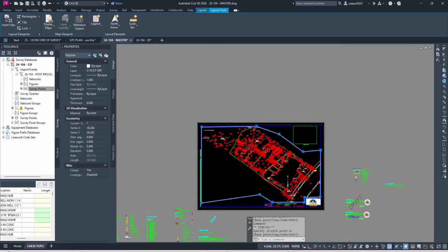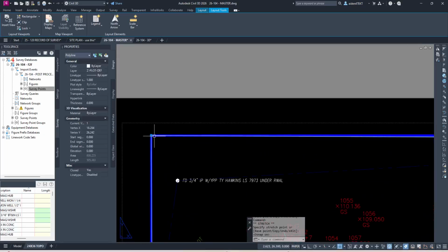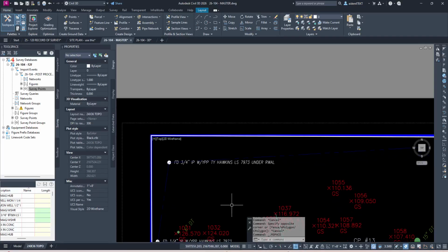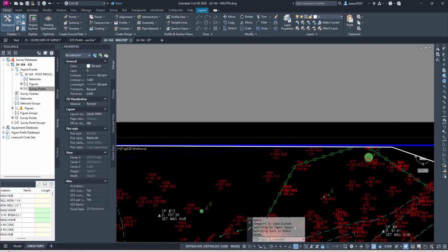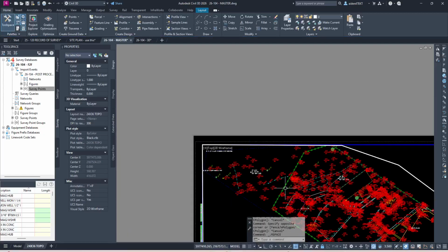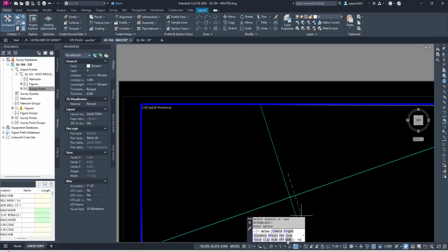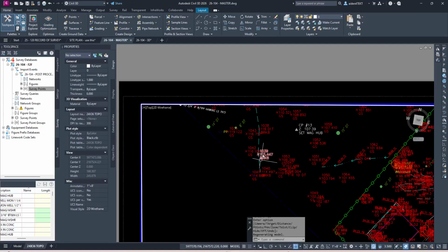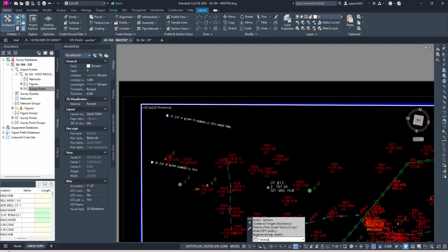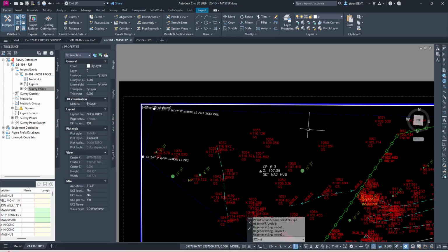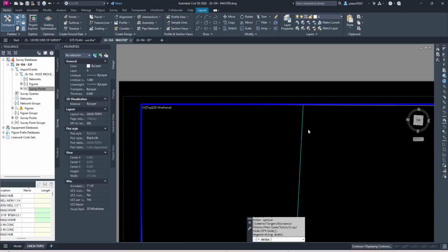So let's see here. We can actually snap this all the way there, and we can just right click and shift this guy up. Lock button there. Yeah, see, we don't want to shave off that, so let's rotate negative, clockwise, a little bit. DVIEW, enter, twist, negative 10. See what that does for us. That's too much. Let's go negative 5. DVIEW, enter, let's go negative 3.